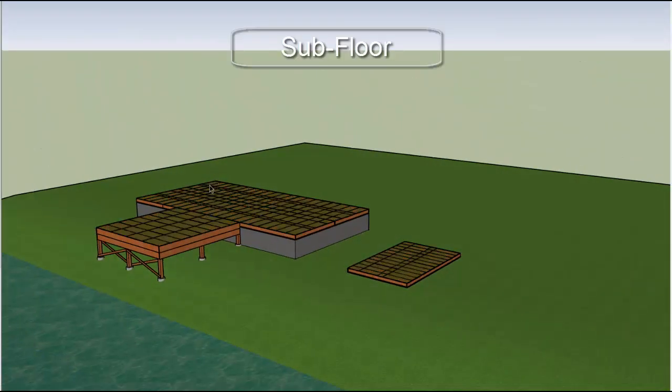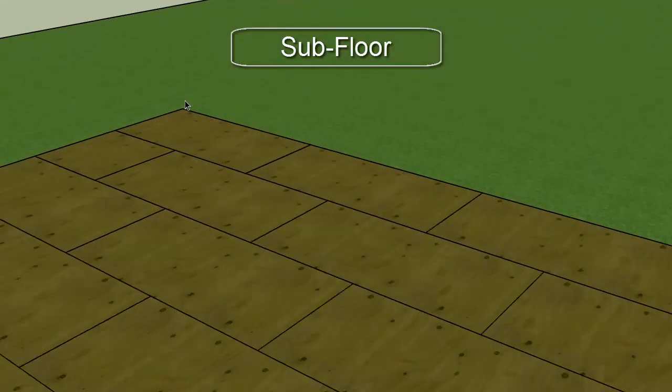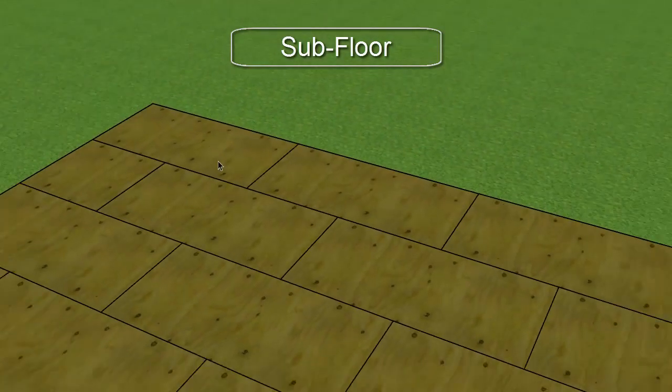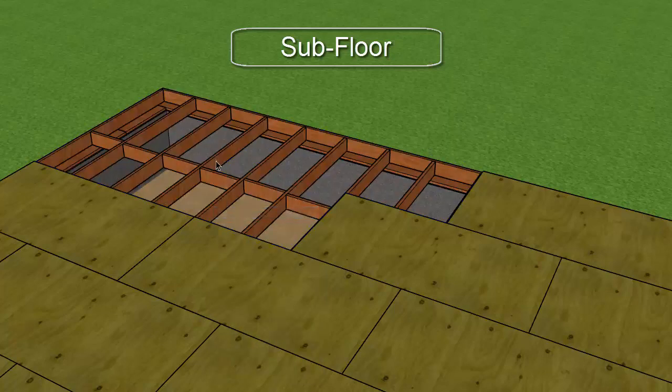Our next component is the subfloor. Subfloors are generally made out of plywood, 3/4 inches thick or greater. However, it can be made out of dimensional lumber such as 2x material, 2x6, 2x4. The plywood is laid out in a brickwork pattern so that the joints are staggered to increase the strength. Also, the plywood is laid out in a manner so that the long edge of the plywood covers as many joists as possible.